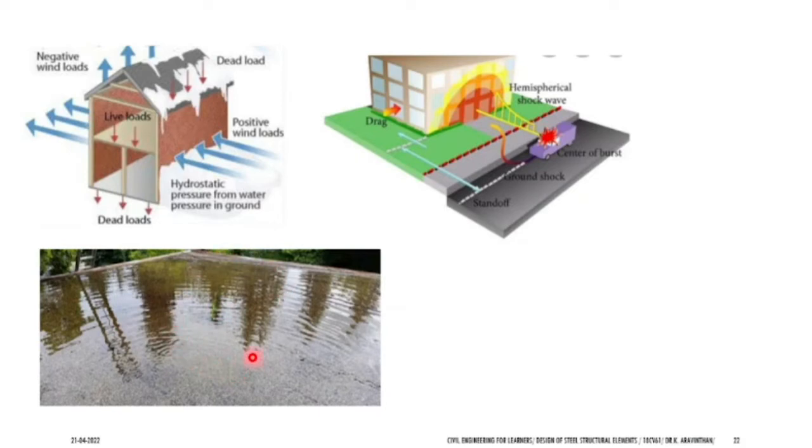For this purpose, 1.5 kilonewton per meter square is added. And also, everyone will be questioning what is accidental load or blast load. See, if you have a structure on a national highway, what will happen if a vehicle crashes on the road? It will impact the house also. You can understand that if any accident happens, it does affect your surroundings, and you have to consider these loads, called accidental load, and then start your building.